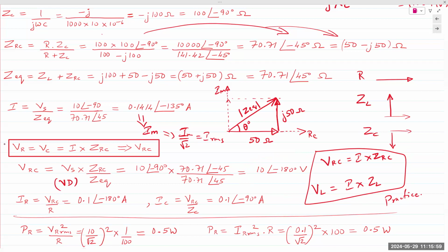When you find the current for the resistor, it has the exact same angle, no difference. Right? No difference. Because the resistor itself doesn't have any angle. So when you take V over R, it's the same angle minus 0. And so voltage and current would have the exact same angle. It's not an energy storage device, so it does not delay the current or the voltage. So they're always in phase. Voltage changes, then current changes at the same time.